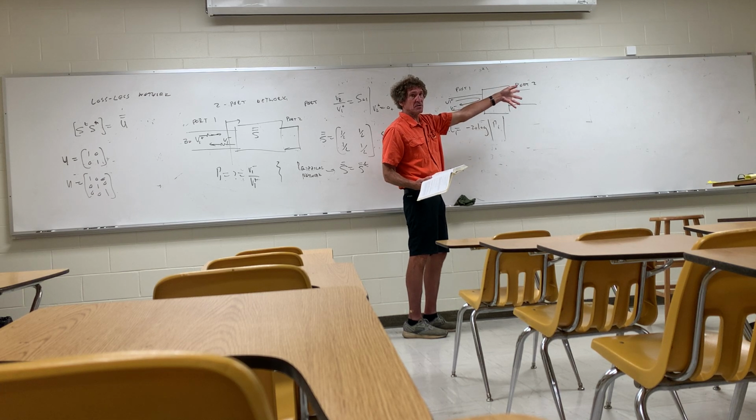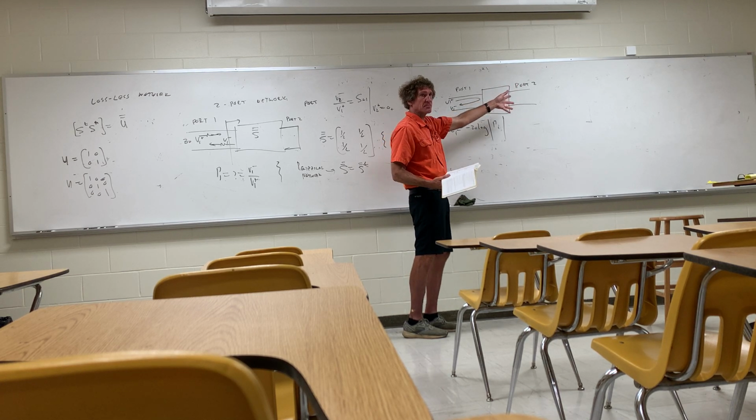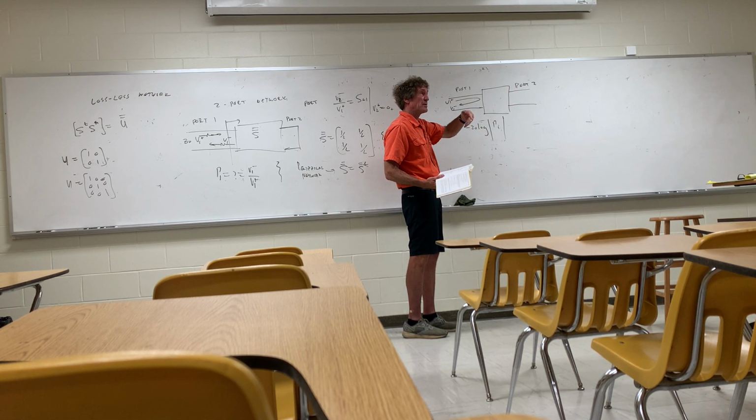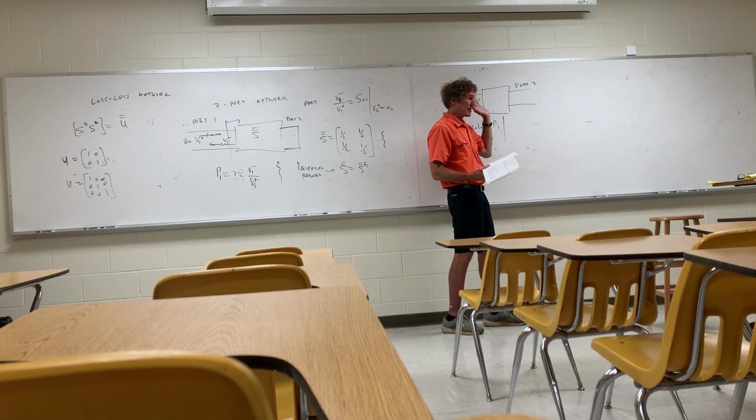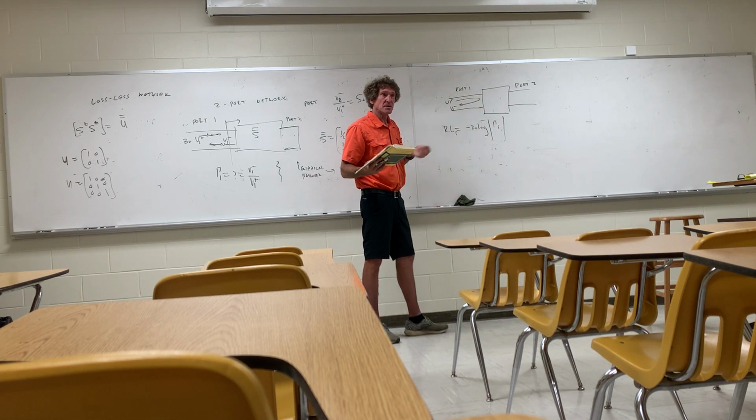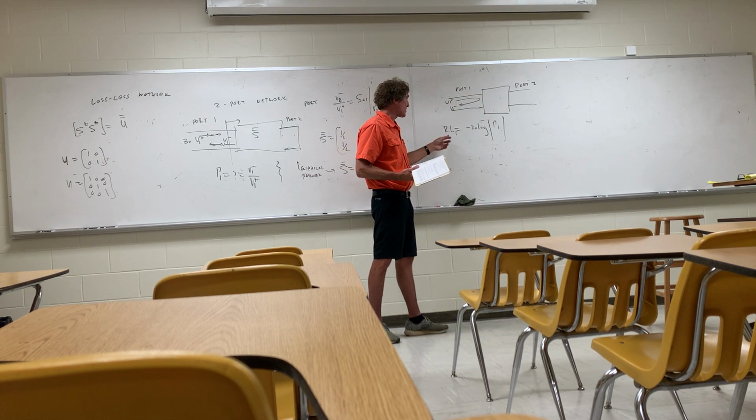Assuming it's matched in almost all two-port networks, if you're using a three-port or N-port, you always want to have a matched condition. You want no reflected wave coming back at you. Right? That would be bad. So usually I just put S11 there. If I want the return loss of port 1, minus 20 times the log of S11. Return loss of port 2, minus 20 times the log of S22.